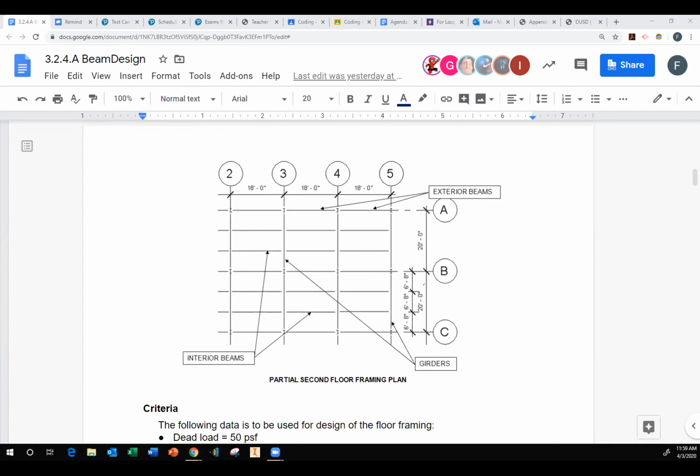Let me annotate it. When we drew the load condition for the beams, we drew a distributed load and it looked like this. And that makes sense because it has tributary width either here or here. But the girder doesn't have tributary width. The beam diagram for the girder looks like this. I'll draw it so that you guys can see it.